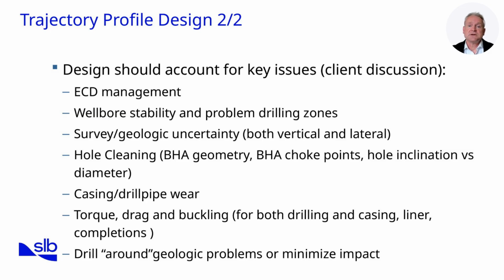Surveying and geologic uncertainty, both vertical and lateral, are more critical in ERD since small positional errors accumulate over long step-outs. Hole cleaning depends heavily on BHA geometry, choke points, and the relationship between hole inclination and hole diameter. Poor design increases the risk of cuttings beds.